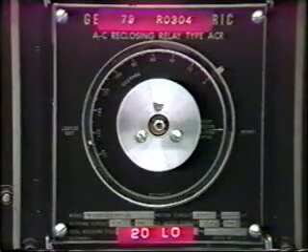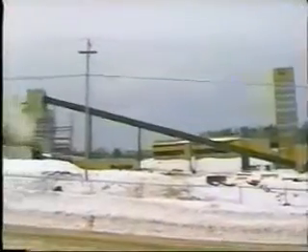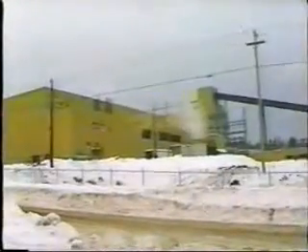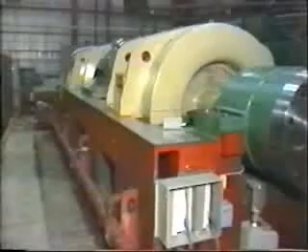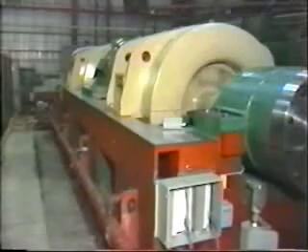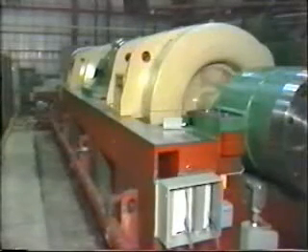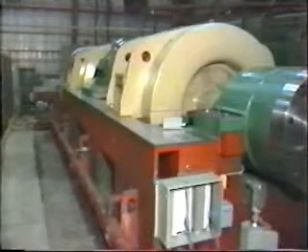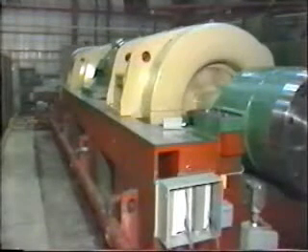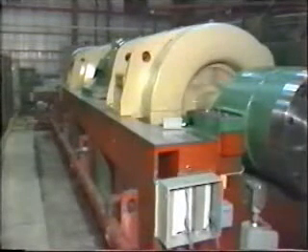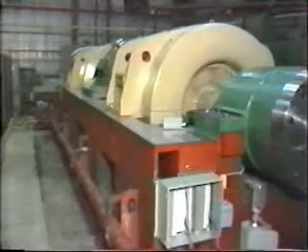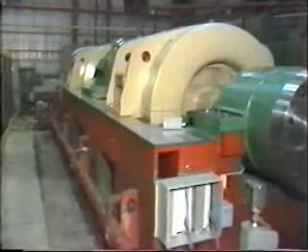For example, the feeder may supply an industrial load which includes large induction motors. Reclosure must be delayed until the motors have time to run down and reduce their residual voltage to less than 1/3 of rated. With synchronous motors, it's preferable to trip the motor before restoring the voltage to the line. You'll remember we discussed this matter in an earlier tape. Loss of voltage relays should be installed on all large motors.